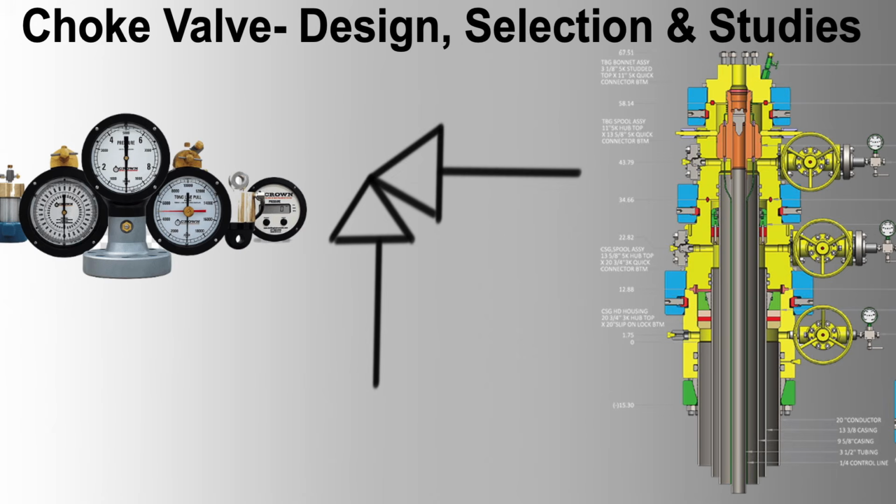Valve design. 1. Type of choke valve. Adjustable choke valves allow for manual or automated adjustment to control flow rates. Fixed choke valves have a fixed orifice size, suitable for applications where flow rates remain constant. Positive choke valves use replaceable beans or orifices to control flow rates in discrete steps. Cage choke valves are designed with internal cages to reduce noise and cavitation, offering precise control.